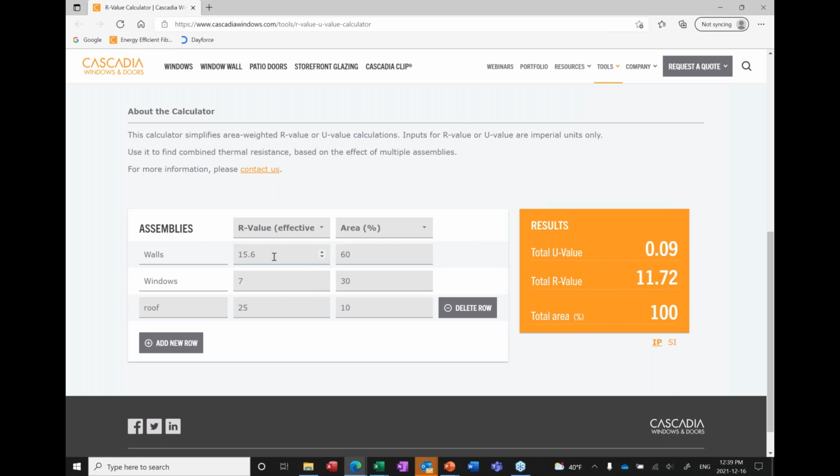And so what does that do? That allows us to maybe reduce the amount of exterior insulation on the wall. We can go down to R11 or something like that, to whatever thickness is required, or gives you the highest floor space ratio or whatever you're addressing in your design, and we're still above that 8. Or if we kept those walls performing well at 15.6, potentially we can change the proportions here.